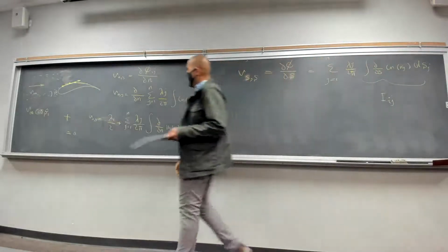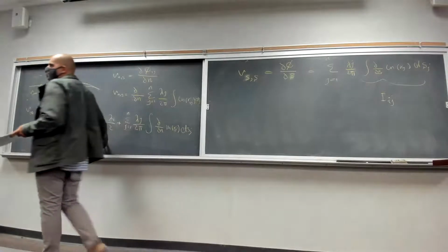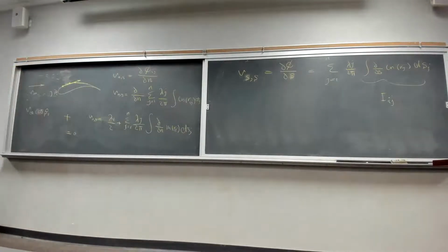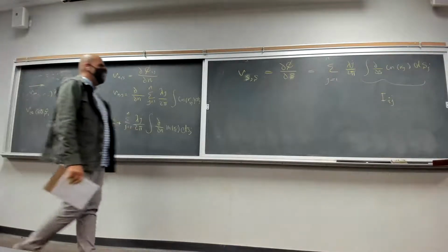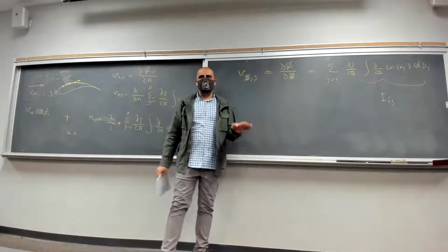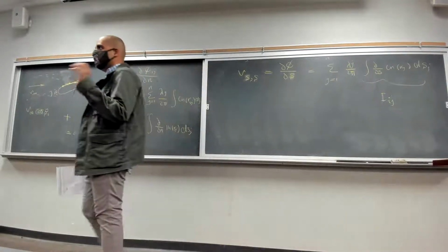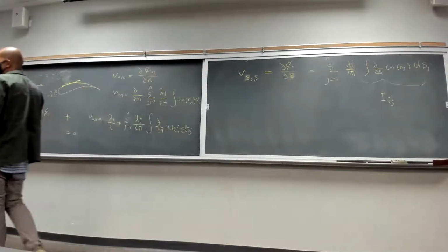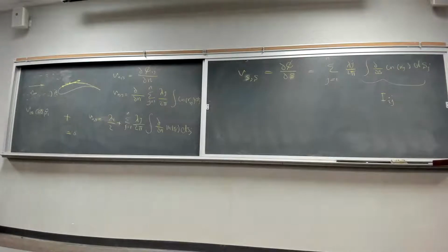So you find the lambda through the system of equations and unknowns, just linear algebraic equations, and then you find the velocity that is tangential to your panel. That was the idea of the inviscid incompressible flow. You only have tangential velocity, right? Okay.